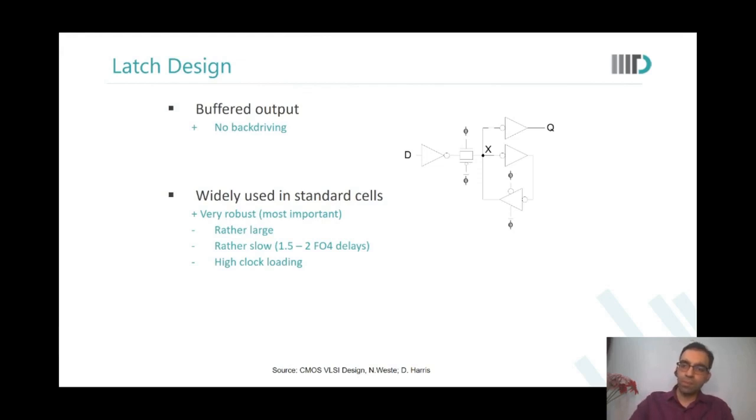Sir, I just wanted to ask, for example, in the complex gate designing that we're doing, if you're not considering the PTL based design logic, then the diffusion input scenario won't occur, right? For us, if we are not considering it, in a transmission gate also there is diffusion input. So for the static and the dynamic, we won't get that diffusion input case because we would be driving the gates only, right? If you're designing the complex gate itself, yeah, but if you design a complex gate with transmission gates, even then there is diffusion input. That is what I'm saying. Yes, sir. Not just PTL, even transmission gates. Okay, right.